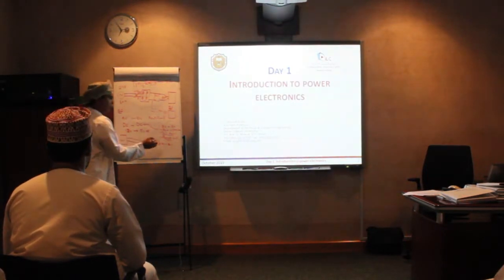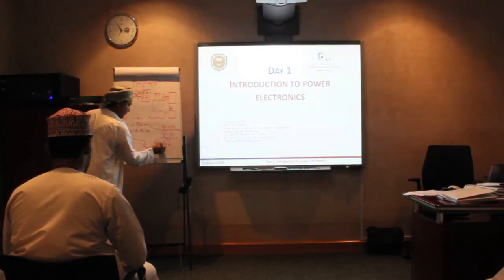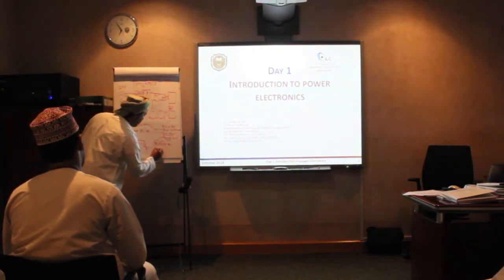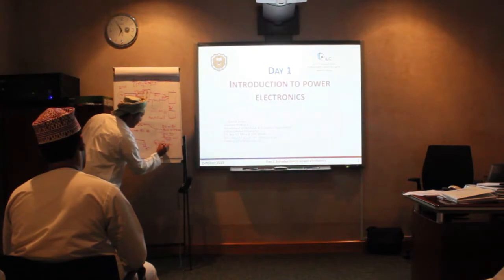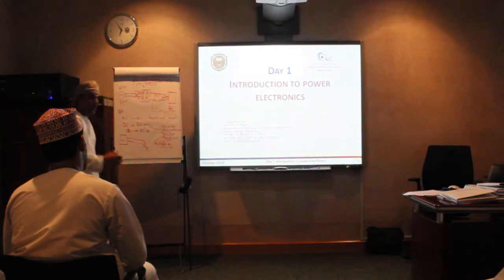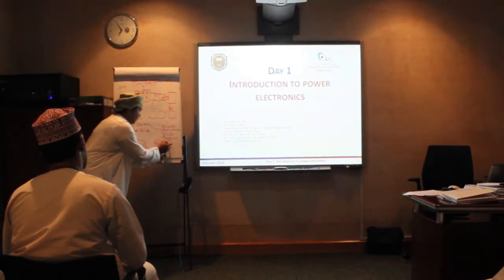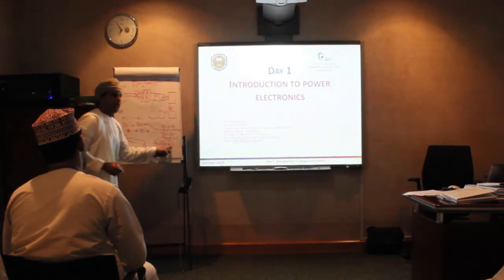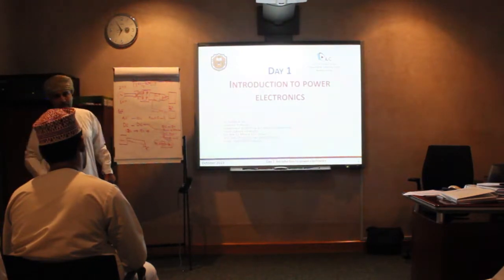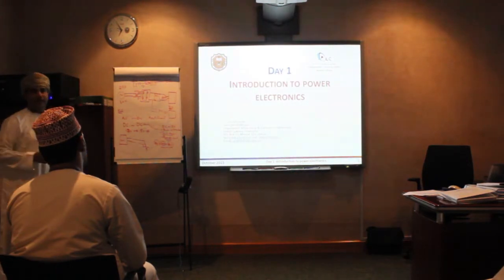Then there is a type of wind turbine known as type 4, which uses power electronics technology with this technique. They change it to DC, and then this DC is converted again to AC, which is a regulated one with the required value. And later on, it can be injected to the grid or used in domestic application or island application.